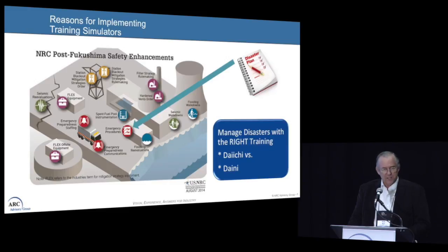But there were a number of particular problems at Fukushima. The first is that the control room went immediately black, all right? The reactor shut down, no problem. It was shut down, the rods were dropped, uranium stopped fission. But as in all nuclear plants, the remaining radioactive byproducts in the tubes continued to generate 6% of full rated power heat. You must cool that reactor, even in the shutdown condition. You must cool it, all right?